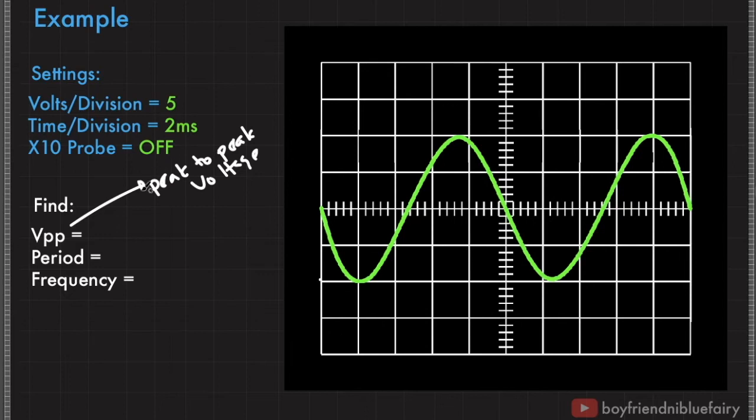However, if you calculate the peak-to-peak voltage, meaning you start counting at the crest until you reach the trough, then if you want to calculate peak voltage, you just have to divide this by 2. Again, it is more efficient to calculate the peak-to-peak voltage first, because when you directly calculate the peak voltage, you are assuming that the waveform is perfectly symmetrical with respect to the zero level of the vertical axis. So again, we will just calculate the peak-to-peak voltage. Essentially, this is the peak-to-peak voltage.